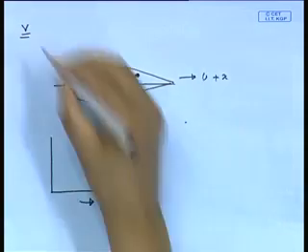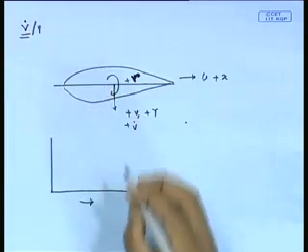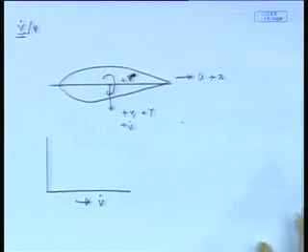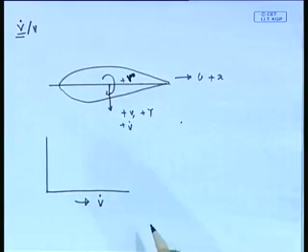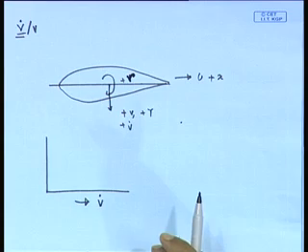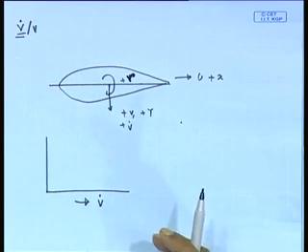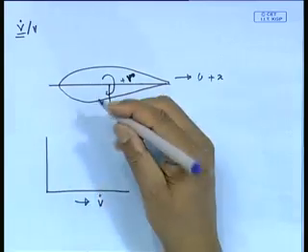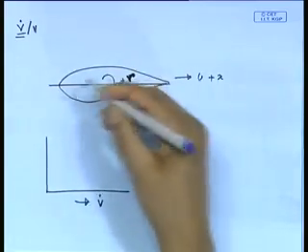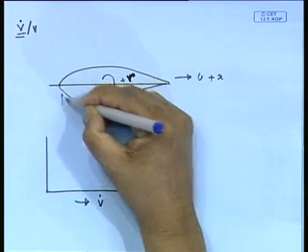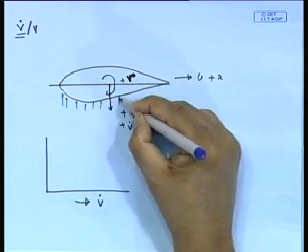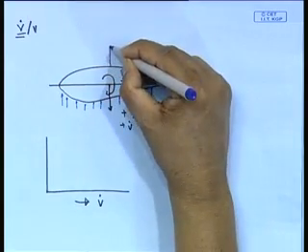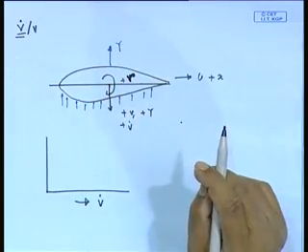Let us take first Y_v̇, v̇ and v. So, I am giving a +v̇, okay, means I am accelerating the body this side. I want to find out which direction and about how much Y will come. Now, you tell me, if I were to push it, accelerate it this side, what would happen? The resistive force, remember I am accelerating this side, the forces resisting will all come this side, right. That means ultimately what I will get is Y will be this side.